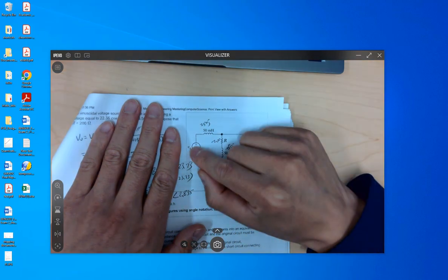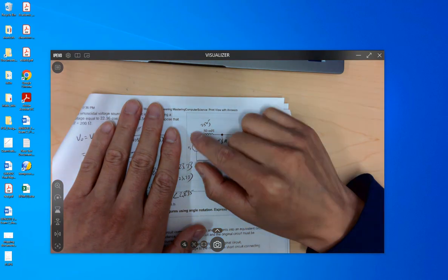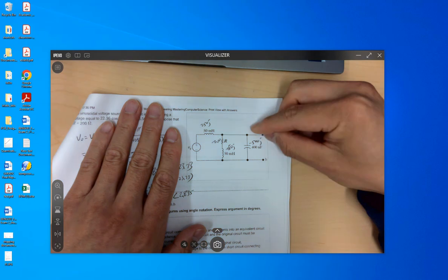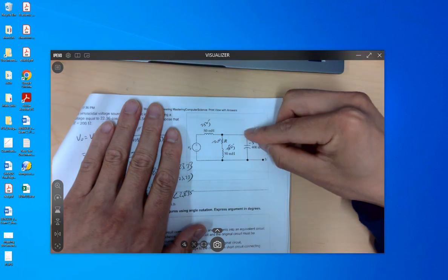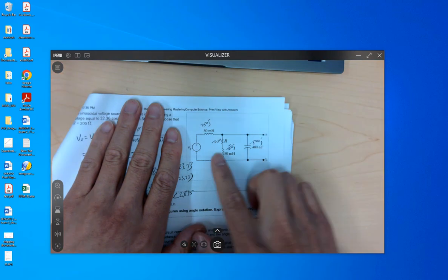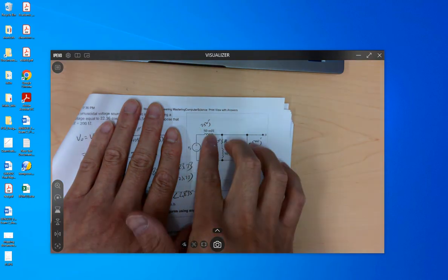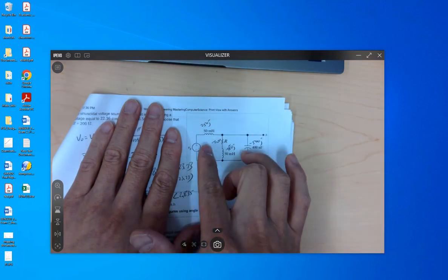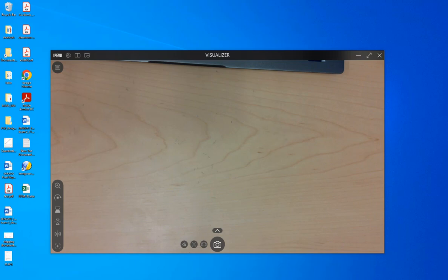This is shorted because the ideal voltage source is getting shorted. It's the wire. Then you're looking backwards. So it's basically one in parallel with these two. It's actually all these three components in parallel, right? I just get a parallel impedance, which will be the equivalent RTH. It's very simple. So now let's move forward with this problem.